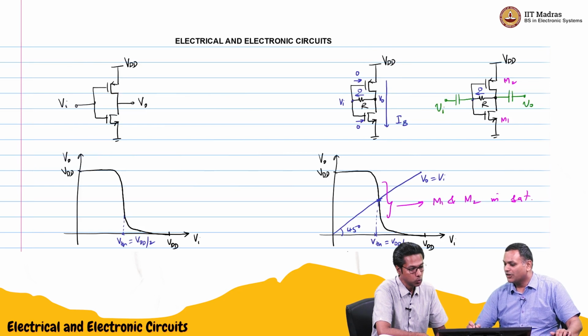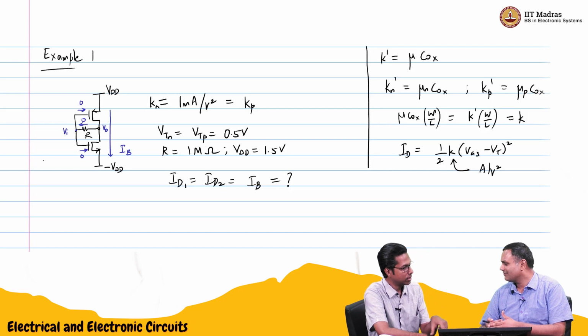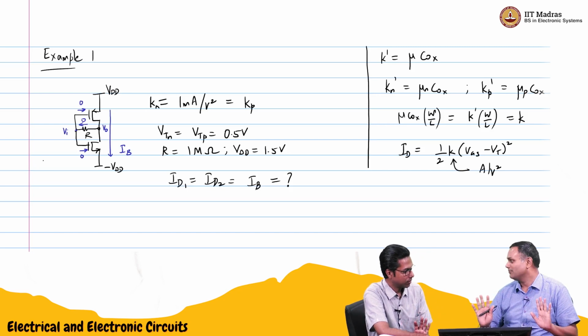Shift to? Because we are not going to sweep from 0 to VDD, we have to sweep the input from minus VDD to VDD. And so when the input is plus VDD, the output will no longer be 0. The transistor will turn off when the input goes closer to minus VDD. So 0 is replaced with minus VDD. That is all in the curve.